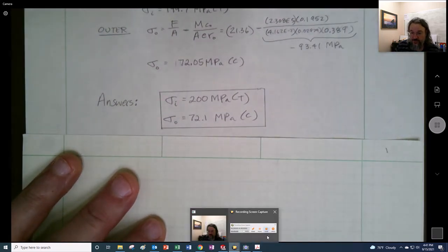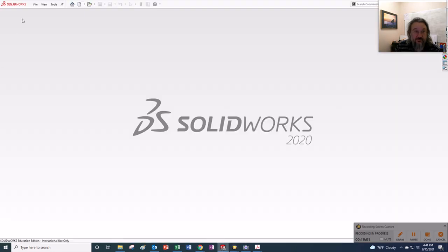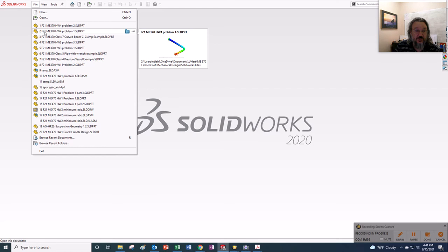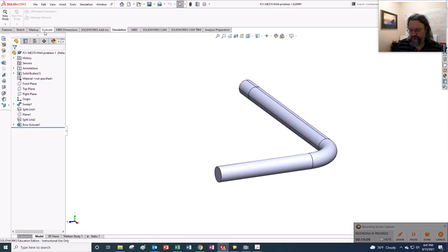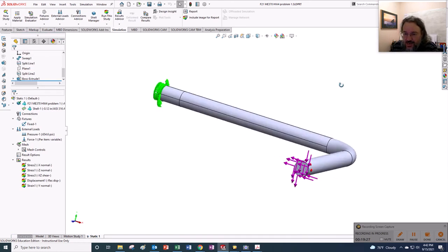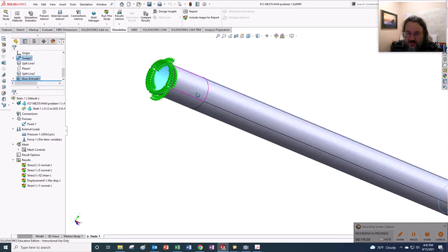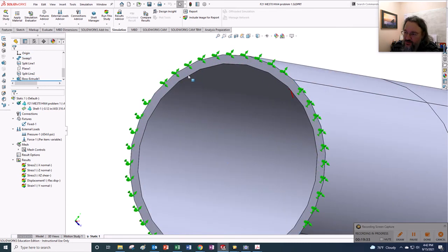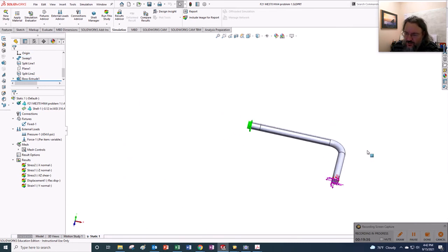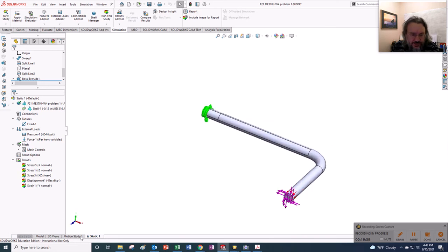And because we can, I made an FEA model of these, right? So here is, I almost hesitate to even show this to you, but I don't have a high degree of confidence in the results for problem 1 because the loads were large enough that I had to turn on the large displacement solver, right? It's the nonlinear solver. And I also decided after my first attempt using solid elements, which didn't go very well, because this is very thin wall right here, I decided to go ahead and use plate elements. So I'll show you what those look like right there.